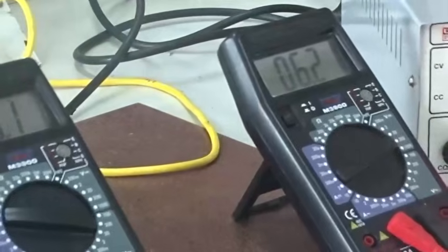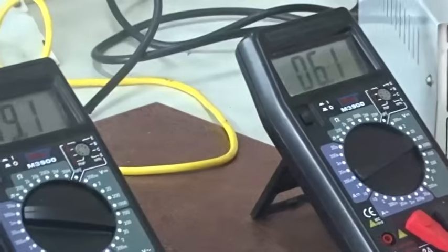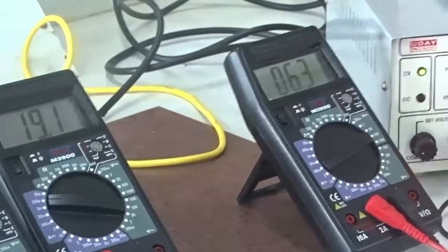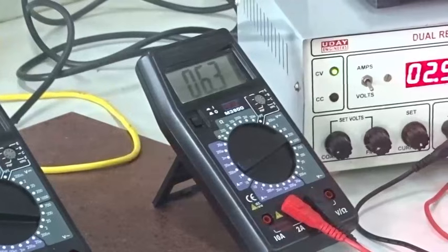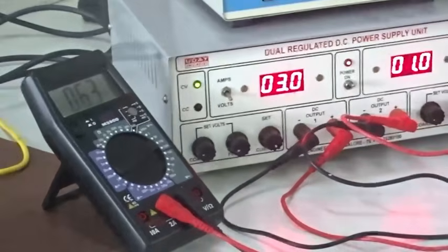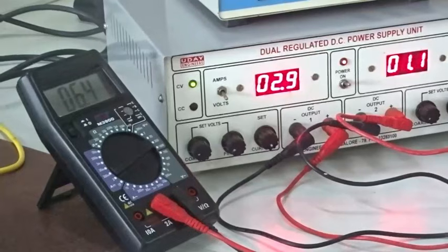IC is 6.2 milli. So IC, you know the range, it is in milliamperes, IB in microamperes. So you have to keep the range of IC at 200 milliamperes. So for 0.5 VCE, you are getting 6.2 milli. So you can increase in steps of 0.5. So this is for 1 volt. At 1 volt it is 6.3. Yeah, so you are getting constant.